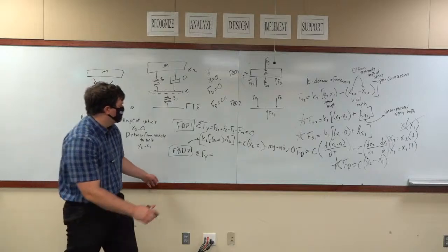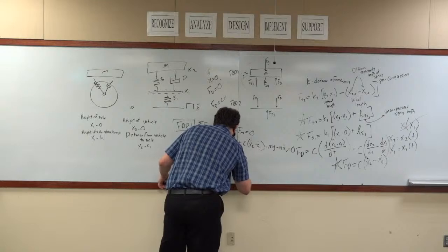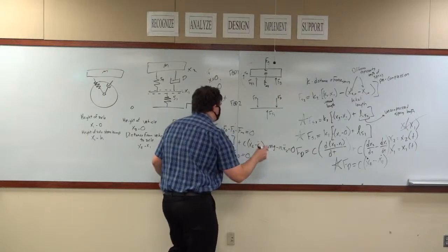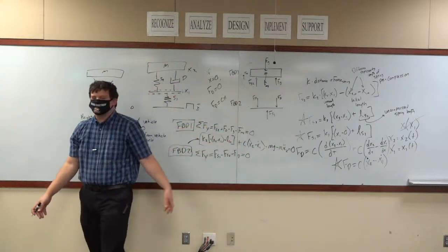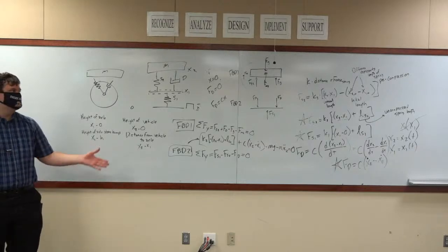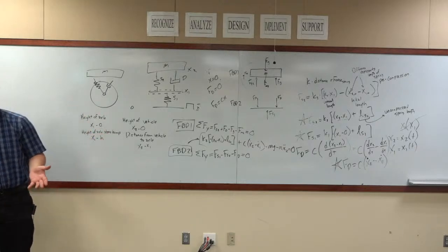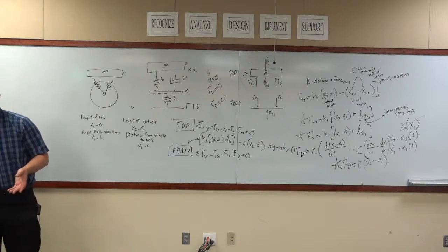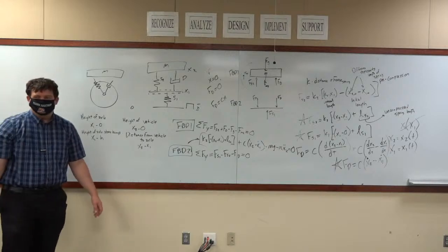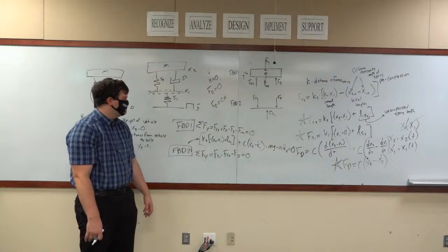FS1 minus FS2 minus FD, and that's equal to 0. We're assuming that the axle is effectively massless because it is a significantly lower mass than the vehicle. Is that an accurate depiction? No. But is it going to change our math much? Oh, heck yes. It's going to make everything a lot easier. Having a second inertial force just means, ugh, blech.